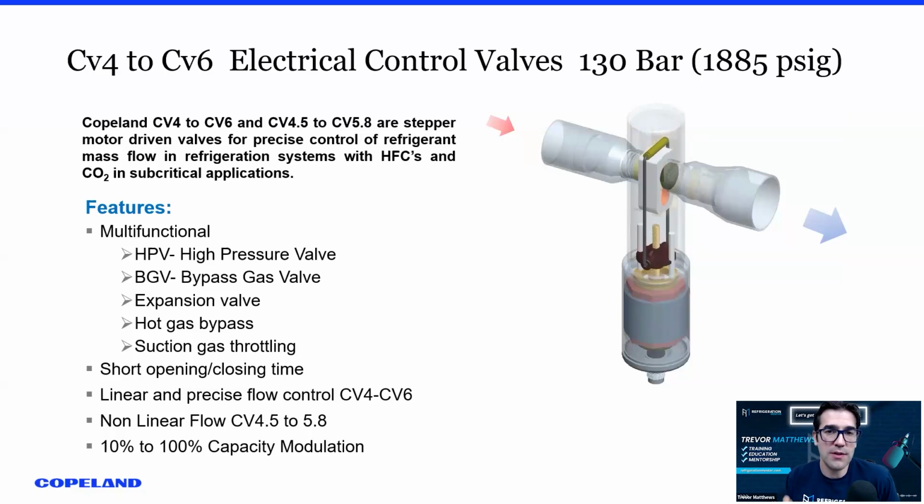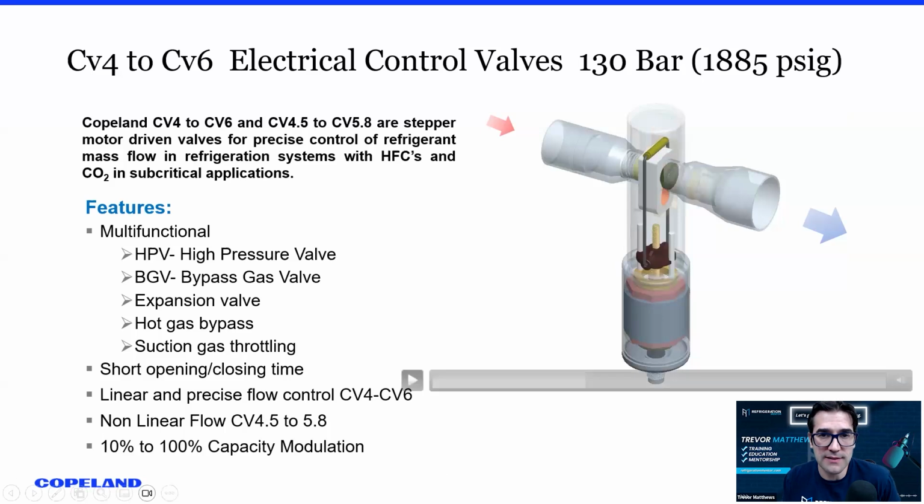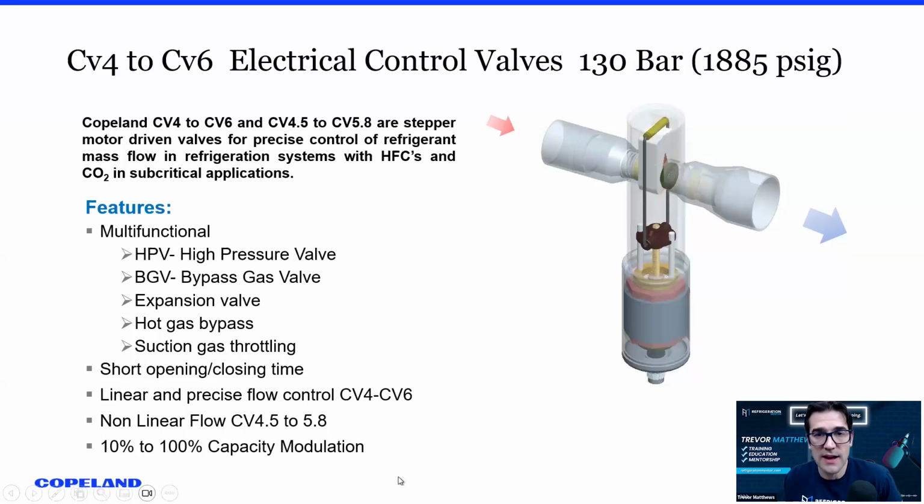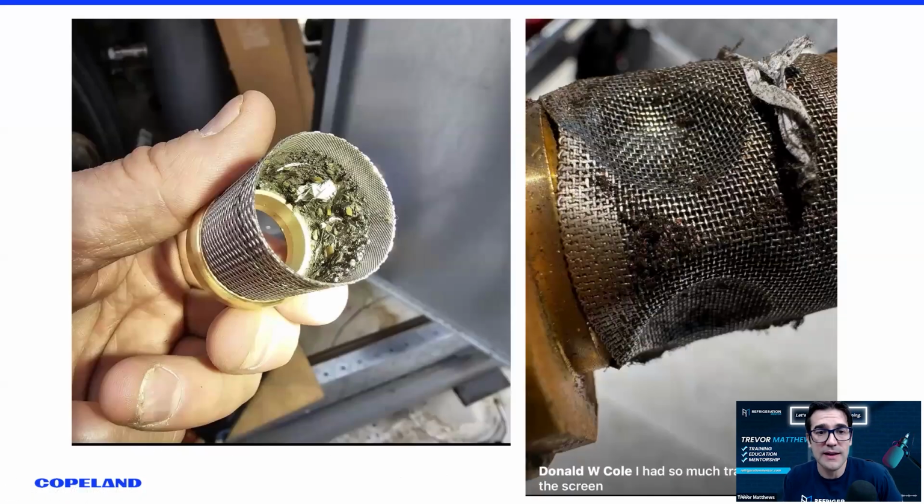The most important thing on those 6 month or yearly maintenance visits is going into these high pressure valves and checking these strainers, pumping down the rack. You got to pump it down properly, know how to isolate it safely, and open these up. You need the gasket kits for them. You can't just open them up and not have the parts for them. You need the other parts for them. And then you got to check the sensors.